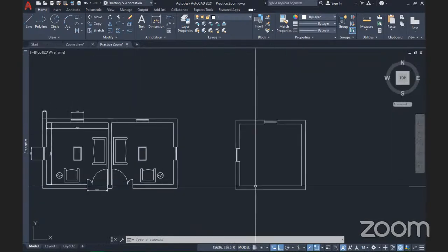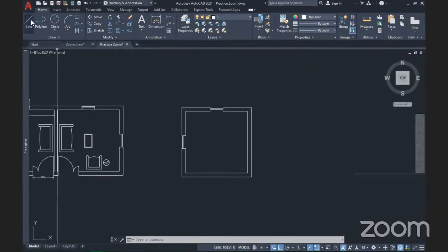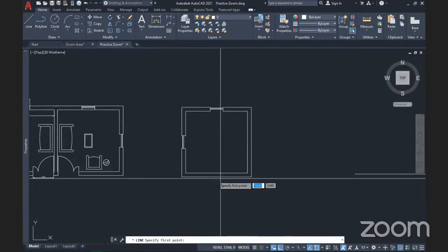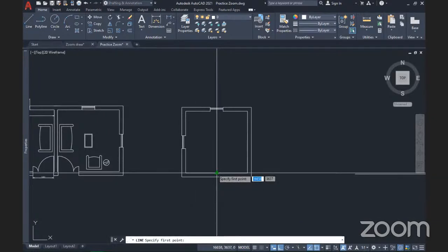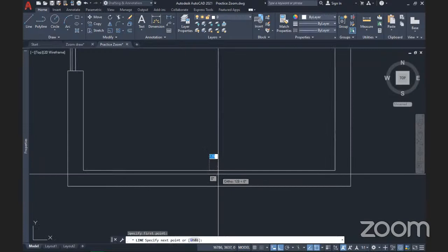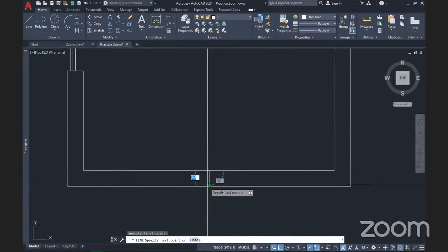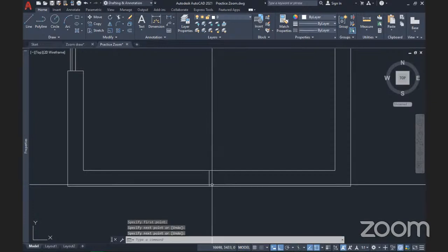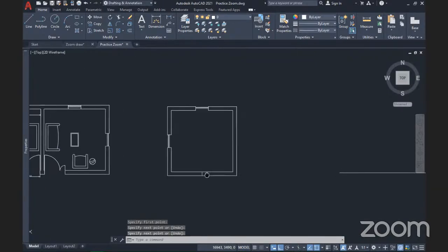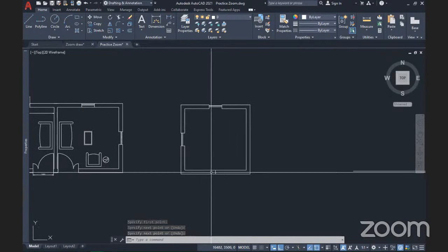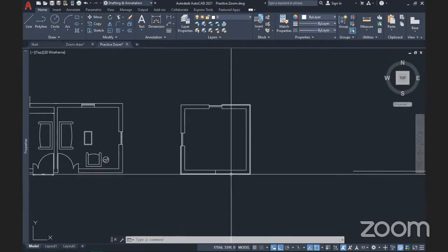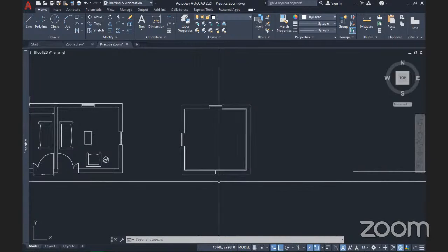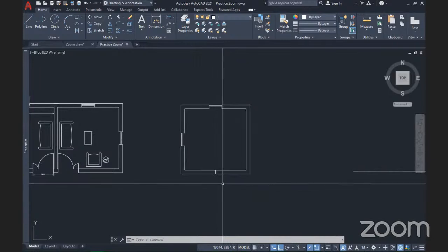Now let's go here and start to construct the door. From the center, I'll draw a line like I did for the window to this other center and click to drop, then enter. So we have it like so. Now I will have to offset both left and right, and both of the offsets will be equal to 1,200.